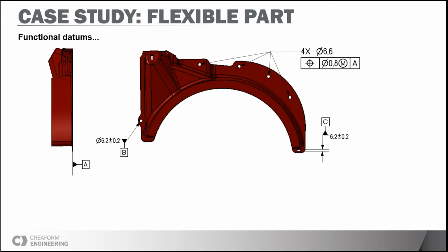So what are we missing? In our assembly sequence, we had these 4 holes. They were bolted at the end. So what do we do with those? We can't really define them as datum since we are already fully constrained with datum A, B, and C. So this is where it will be a bit different with flexible parts. What will be different is we will have to specify the constraint state of the part.